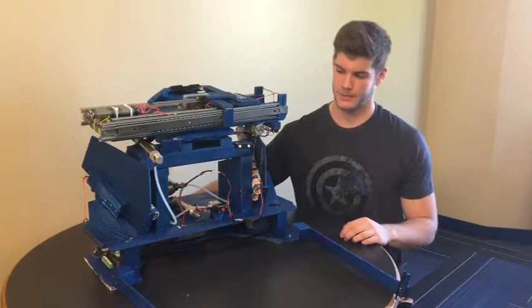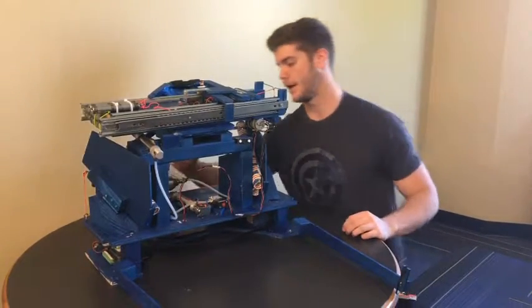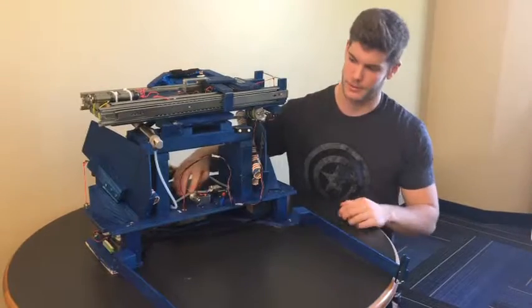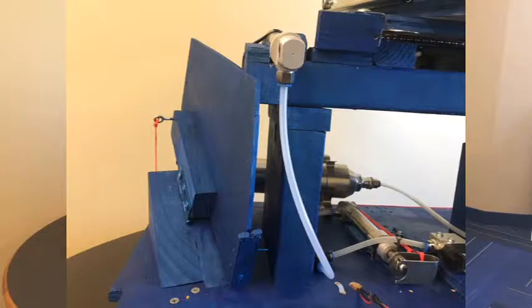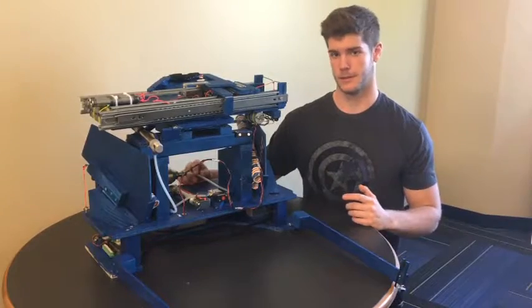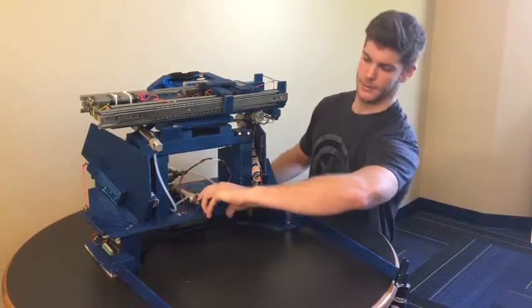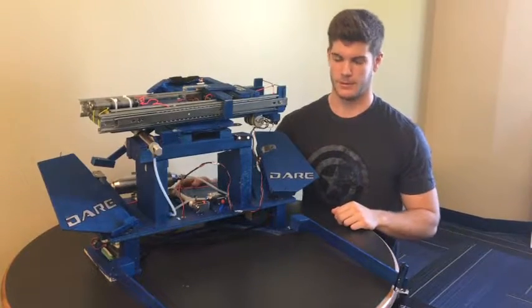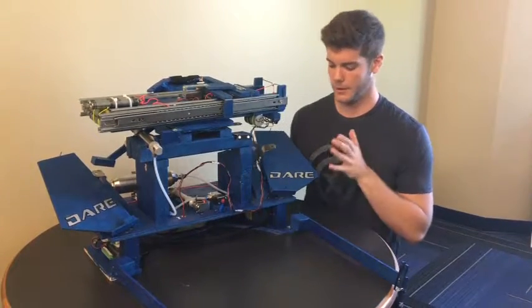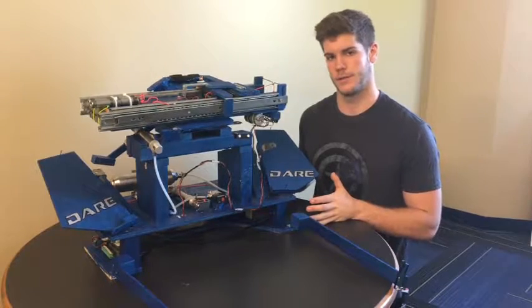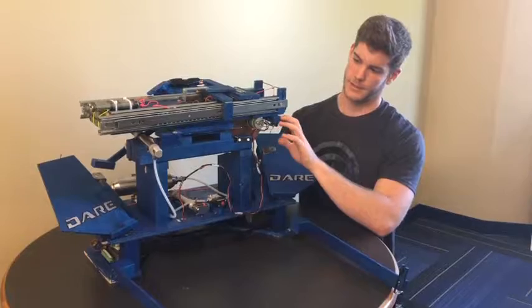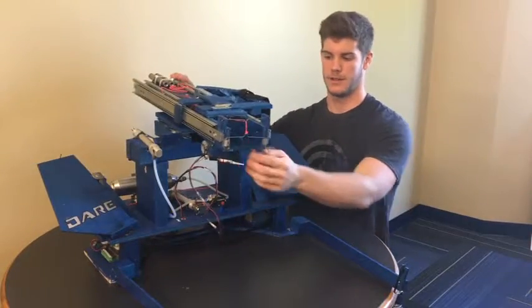After the rock collection, the second subsystem is fired by this valve, which releases the air from the tank into the 2 actuators here and here. The first actuator fires the tennis ball clearing mechanism, just like this. The second actuator is crucial because it allows us to maintain the horizontal orientation while still reaching the center mountain ridge. When it fires, the entire top system rotates and locks into place here.